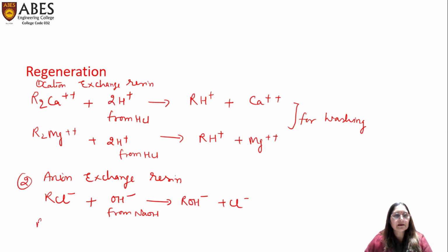Similarly, exhausted anion exchange resin reacts with dilute NaOH and again it will regenerate the ROH-, that is the anion exchange resin, and release the SO4--.